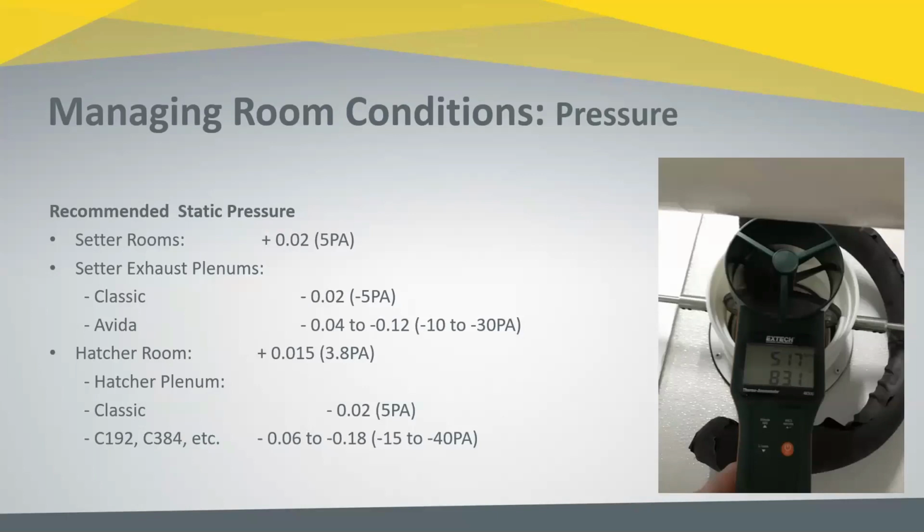This is kind of a practicality of how do we take measurements. Liam is asking, we have aux fans on our hatchers. When I take my CFM measures, am I supposed to do that with aux fans on or off? So for a hatcher machine with an auxiliary fan, the first measurement you take is with the fan off. And with the fan off, you want to set your plenum pressure in order to achieve in that range of about a 7 CFM per 1,000.